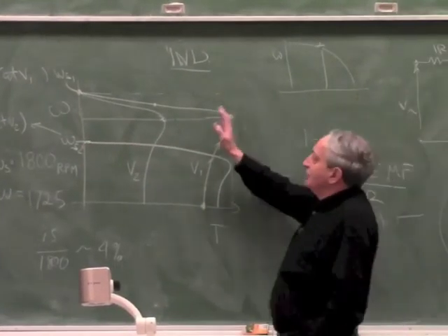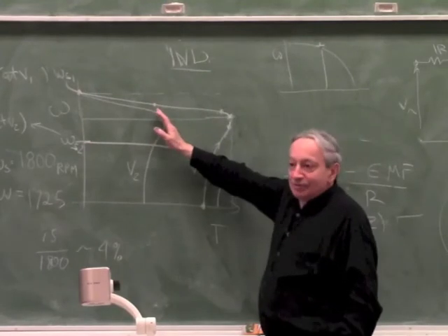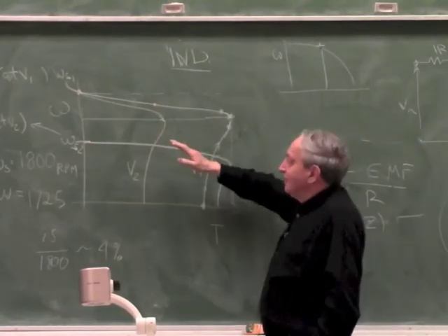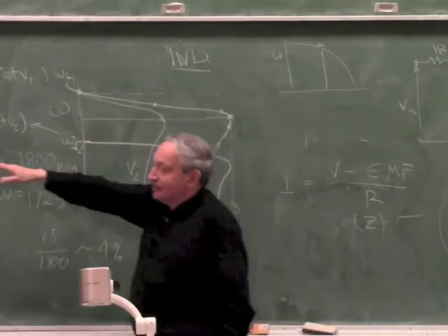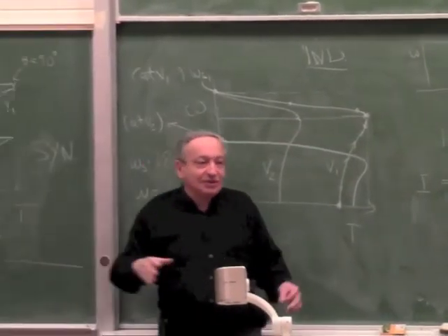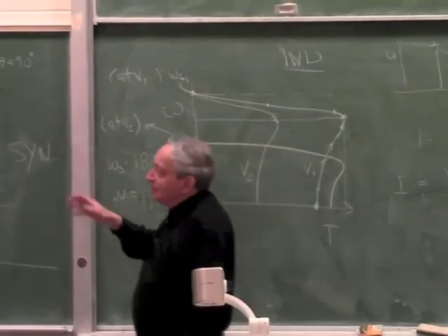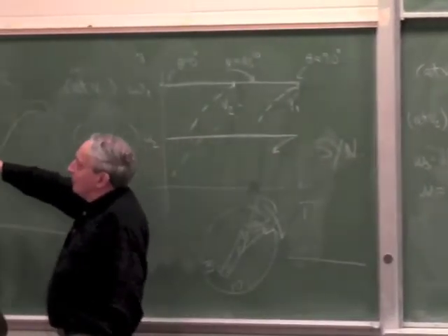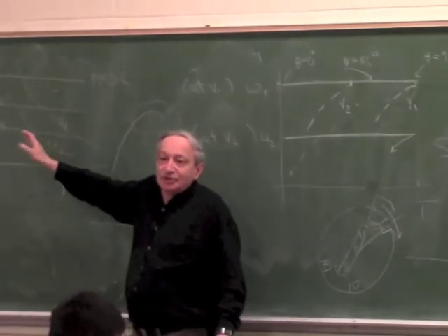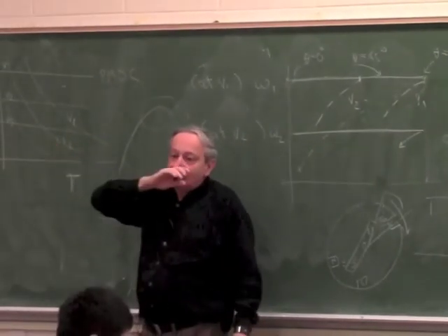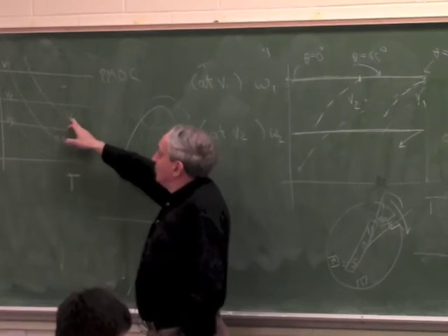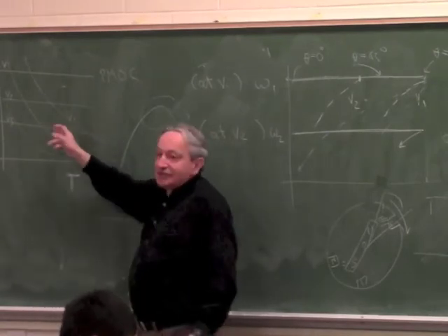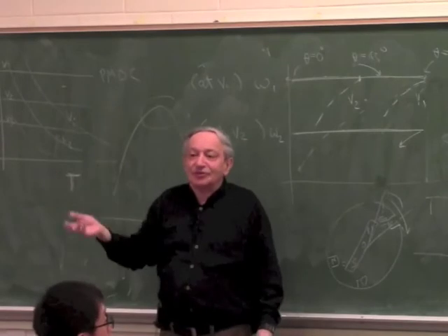Just changing the voltage changes the torque, the maximum torque. If I want to lower the speed, I have to change the frequency and the voltage. Same as here. So you see what's more confusing here, because on a DC motor, there was only one parameter in control, voltage. That's it. Because even the torque I can adjust with voltage. If I want at some point more torque, I just can increase the voltage, the motor will give you more torque for that load.